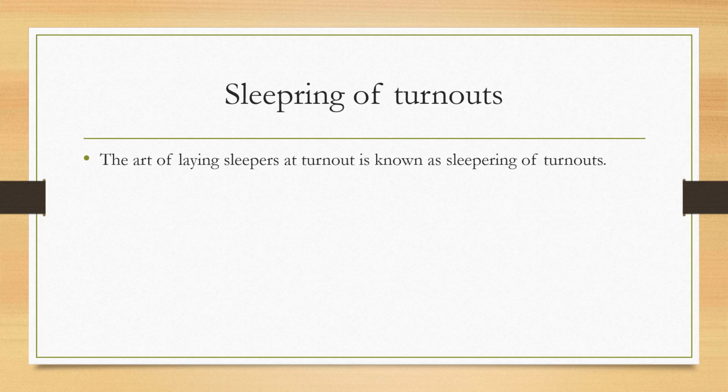Through sleepers have the advantages of maintaining both the tracks at the same level. They have no difficulty in packing the ballast during maintenance. This method of sleepering should be preferred if through sleepers are easily available.